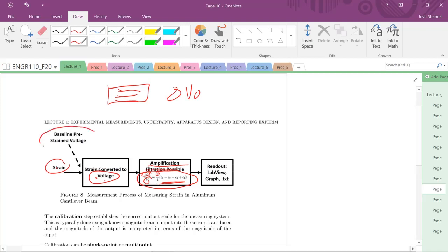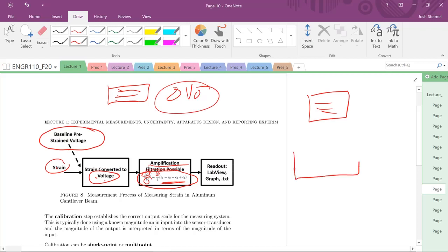Now, there is a really cool and probably a little bit hidden calibration step. Once you apply the strain gauge, because you have to push down really, really hard on that strain gauge with your thumb, often you'll pre-strain the material. So remember, this is the change in the voltage. Even when there's no strain in your material, so on our beam, we have our strain gauge.